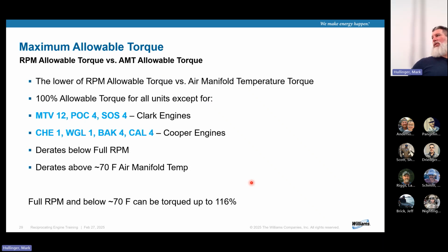So if the gas controllers are in the room, there might be some percentage of torque and flow that we could actually gain on our system that maybe we aren't using. A lot of folks get jitters going above there, but it's not every engine, and the controls will limit you right at 100% torque.